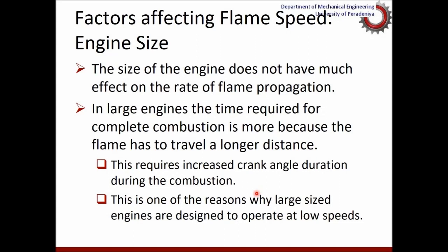You have to leave more time in the engine process for burning to take place. So accordingly, large engines usually run at lower speeds, allowing the necessary time for combustion to complete. So that is one of the drawbacks with large size engines, where you need to allow more time for combustion. That means you will have to run the engine at lower speeds.